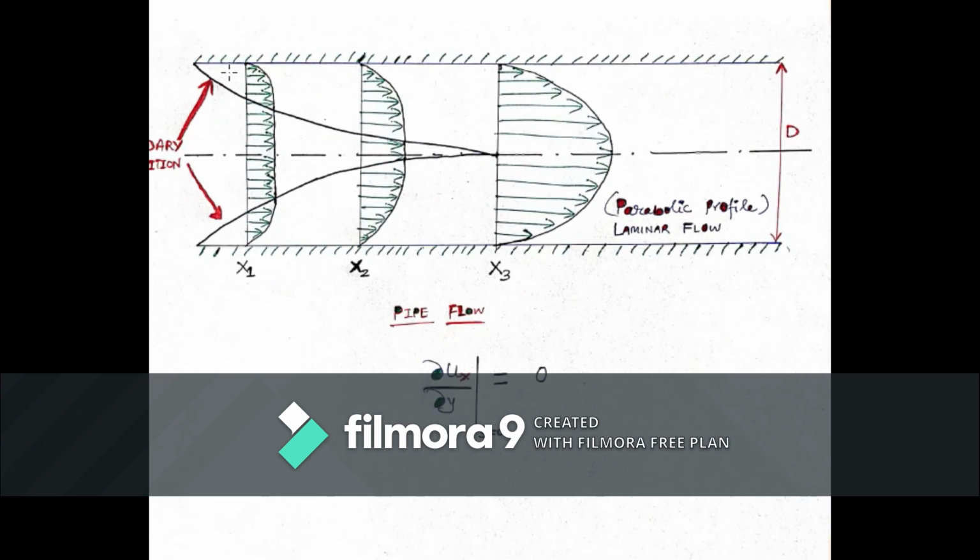Here you can see the two boundary layers for the pipe flow. Till the entrance length, your velocity profile keeps on changing, and this is for a laminar flow. So outside the boundary layer, your gradient is 0 because your velocity is constant. Here also you can see outside the boundary layer, your gradient is 0 because the velocity is constant.